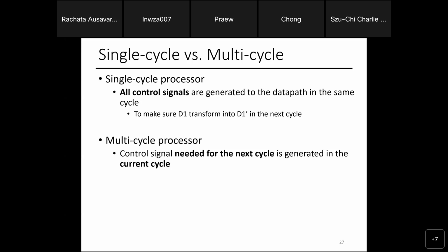But if I have to do a multiply, with the 2 inputs ready and fed to the multiplier, I need to wait at least 3 cycles to finish the multiply. And every time I clock, I save the internal state of my multiplication. But this allows me to clock a lot faster, which means that if I have a lot of add instructions, the program gets faster quickly.